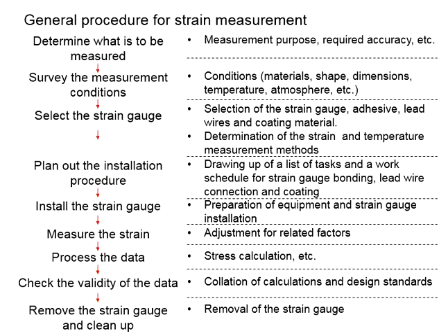You will need to consider whether the strain gauge is to be embedded within the test specimen or it is merely on the surface of the test specimen. For example, some strain gauge is attached to reinforcement bar. The strain gauge will need to be protected with suitable coating material. Leave the lead wire out before you cast the concrete. While casting the concrete, be careful with the regions that you have the strain gauge installed. Any damage to the strain gauge will result in no readings being acquired from that strain gauge.